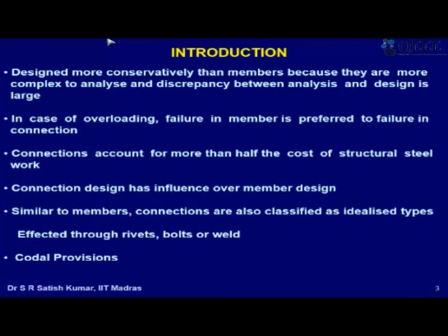We saw in the limit state chapter that not only connections, even a structure, when we are trying to analyze, our analysis gives only an approximate idea of how the structure is going to behave. So there are issues like stress concentrations and non-uniform state of stress, sometimes buckling, residual stresses. All these issues we are not able to capture in our routine design. So we will try our best to capture as much as possible, but then we will always have some margin of safety.